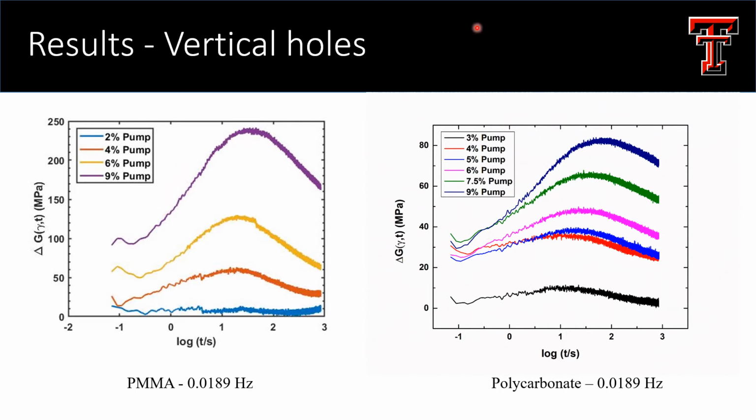The peak intensity of holes increased with increase in pump amplitude, but polycarbonate showed relatively weak intense holes compared to PMMA. These results provide evidence to support the hypothesis that the hole burning event in deep glassy state is related to the occurrence of strong beta relaxation as evidenced by the high intense vertical holes in PMMA. At 2% pump amplitude, PMMA did not show clear vertical modification.